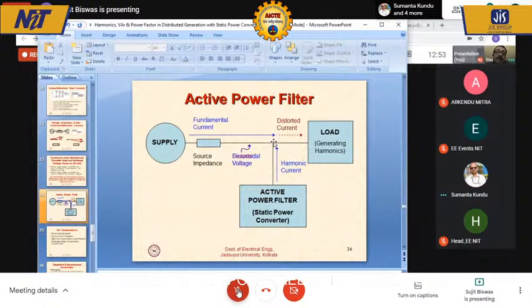In this slide, if at any instant the particular fifth harmonic current is flowing from left to right, how do we decide? Because in AC, there is no real direction of current. It is decided by the positive half cycle and the negative half cycle. So if we put a phasor from left-hand side to right-hand side, as we show here, then at the same instant, the harmonic current generated by the active power filter for that particular harmonic should be as shown here, such that at this point they will sum up to 0 and there will not exist any component on the left-hand side.